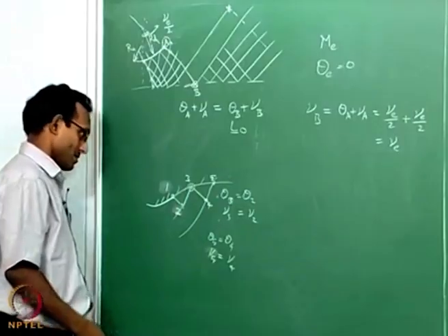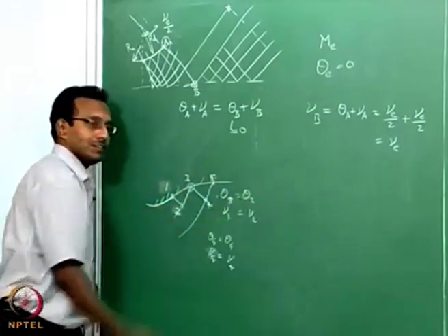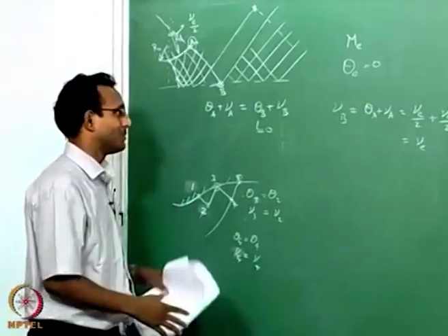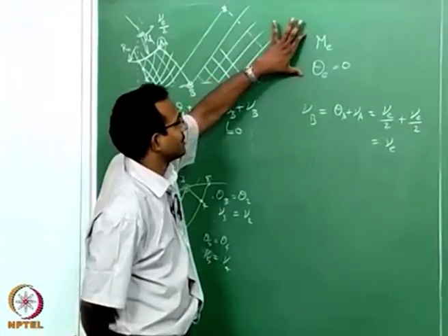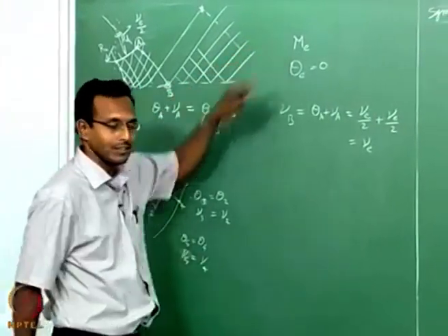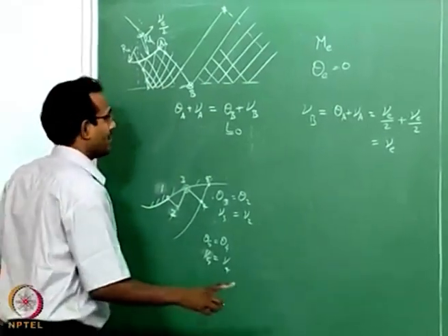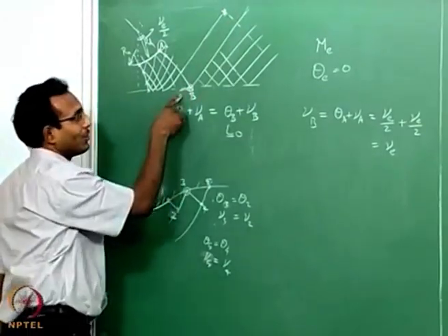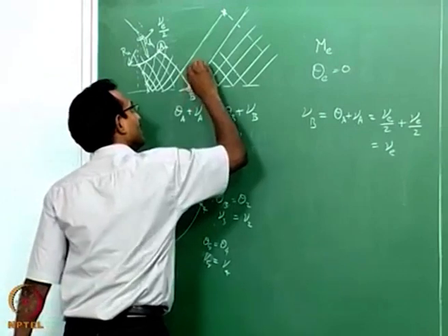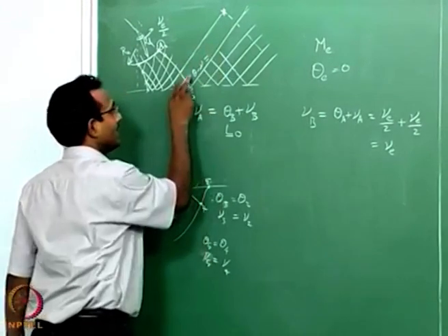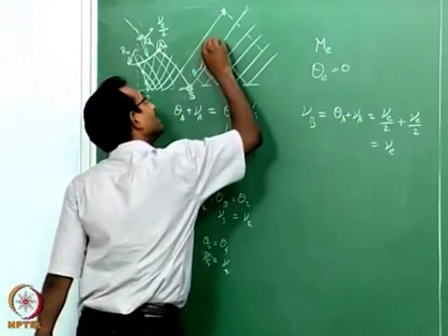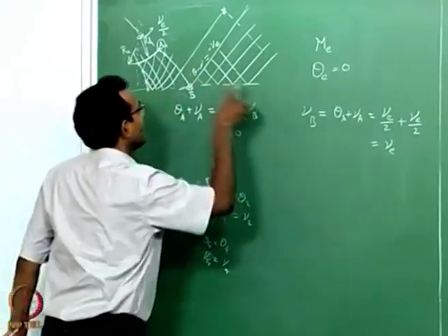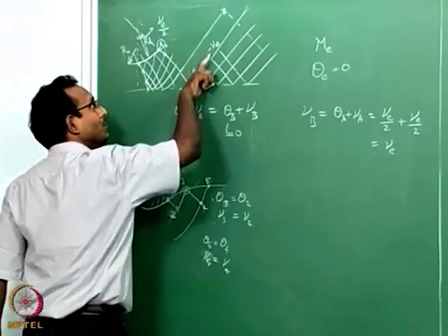Okay. And once you get this surface, we have solved and we have created a new nozzle which will give me that desired exit conditions, theta e equal to 0 and exactly that Mach number. How will I make sure that I have done the correct thing? The last characteristic that is going from here is a positive characteristic. So, theta minus nu is equal to constant, theta 0 and nu is nu b, minus nu exit will be the value, nu b is here. Okay. I will get theta minus nu equal to constant is equal to minus nu exit.